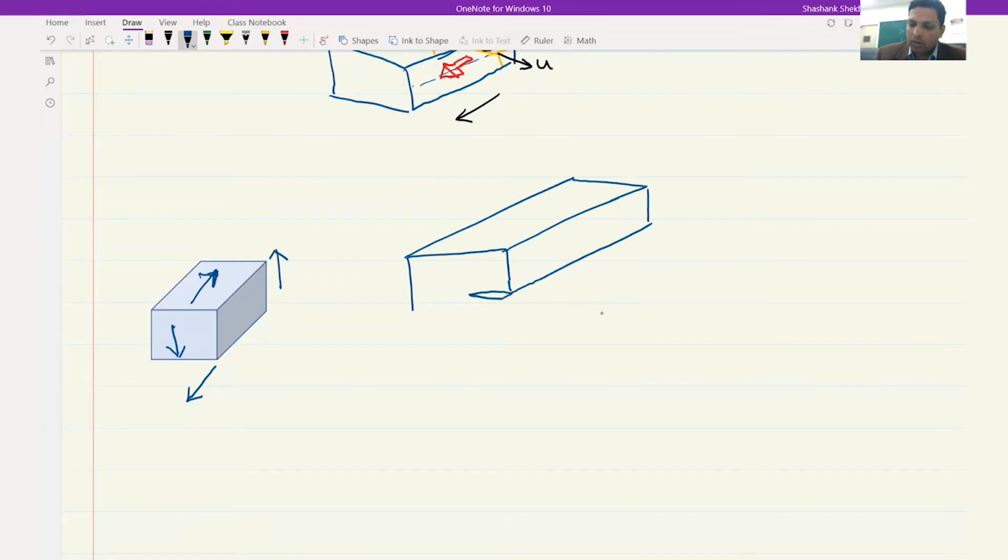So a dislocation has been generated. Because of this, you would get a screw type of structure in the material, and it would look like this. So this has come out better than what I expected. And here is a step, a partial step, and your screw dislocation is all the way from here to here. This is the screw dislocation line, and as we know, for a screw dislocation, this is the line vector, and this is also the Burgers vector. So both of them are along this line, and you are applying a stress like this.